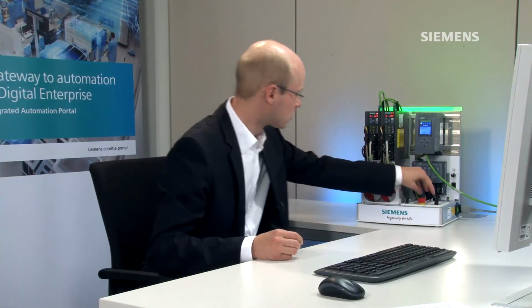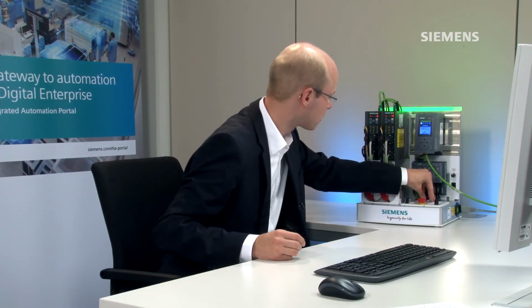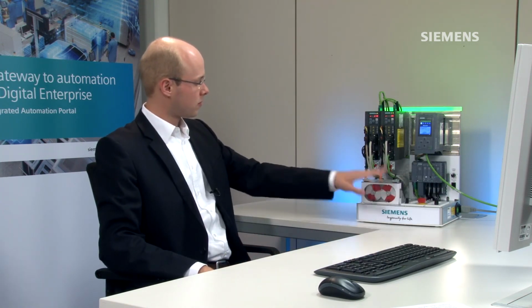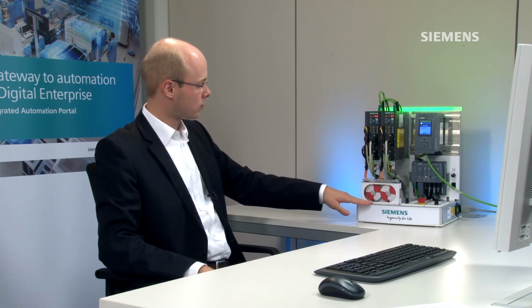That's it. We've managed to couple both axes that quickly. Let's once again review the final result here on the configuration. We see the right axis moving continuously, and the left axis is coupled via the cam disk. As you can see, we quickly created the cam disk, defined the position ratio, even optimized the cam disk, and coupled both axes to one another in the program.